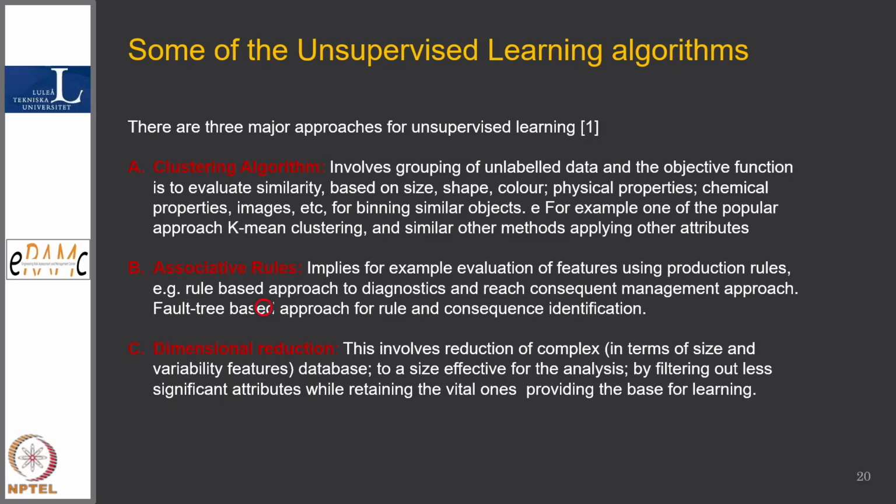So if that information or data is imprecise, I will apply fuzzy logic. The fuzzy logic defuzzifies them and again makes them into crisp output. So for that output, there are centroid and so many other things, and then membership functions, rectangle and various functions are there, triangular or trapezoidal. So those kinds of algorithms we have to use for association of data.